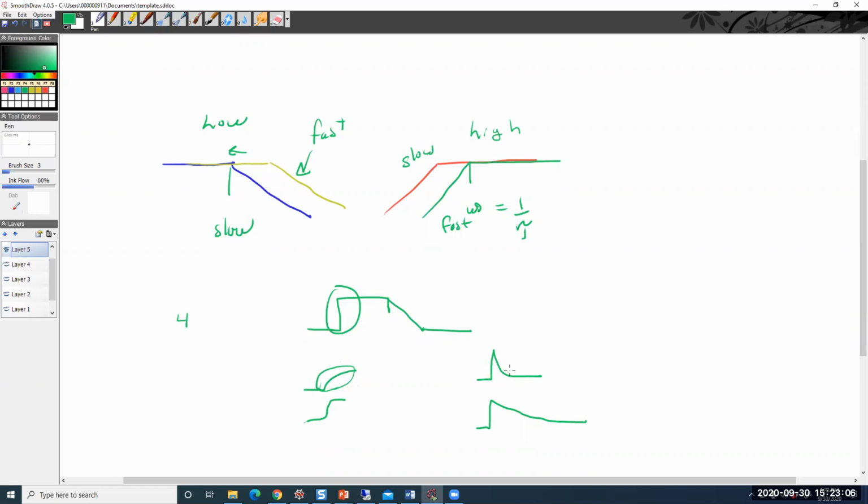High pass filters detect edges, or they're trying to calculate a slope. Since the slopes are 0 here, the output goes to 0. Low pass filters pass DC. So when I put in a DC signal, it's going to stay constant. It doesn't decay to 0. Now in here, the high pass filter will eventually try to be the slope, because that's what they also do.